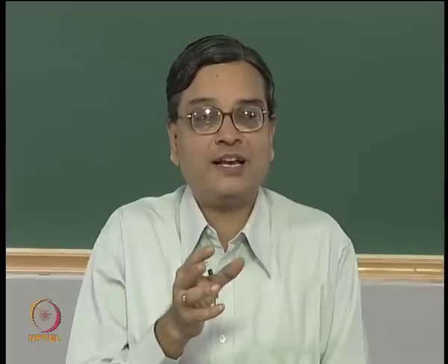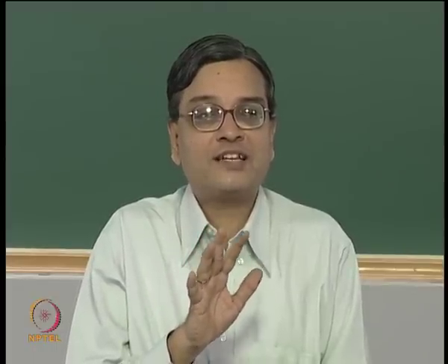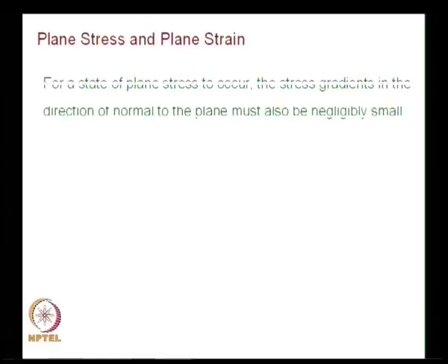So, we have adapted a slight variation in the definition of what is plane stress and plane strain in the context of fracture mechanics. So, you have to recognize that there is a difference. And you will also have to note, for a state of plane stress to occur, the stress gradients in the direction normal to the plane must also be negligibly small.